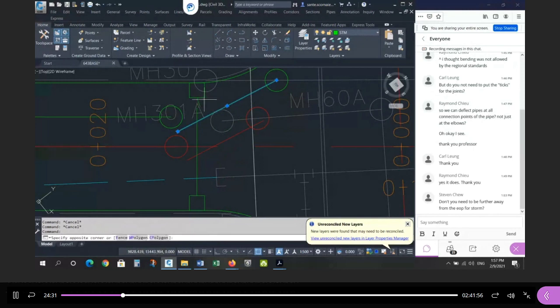This pipe now got further away from the structure, and then you could just determine, okay, I'll put the maintenance hole here, and I'll put the maintenance hole here, and have this connection. I can do this with my storm sewer, and I can do this with my sanitary sewer. Sanitary sewer here and here. Then I can connect this to the actual structure. I'm not sure if that's allowed. That's one way of doing it. Or you could just service the catch basin off the side, the midpoint here, and connect downstream of the maintenance hole that way. So that's another connection you can make.